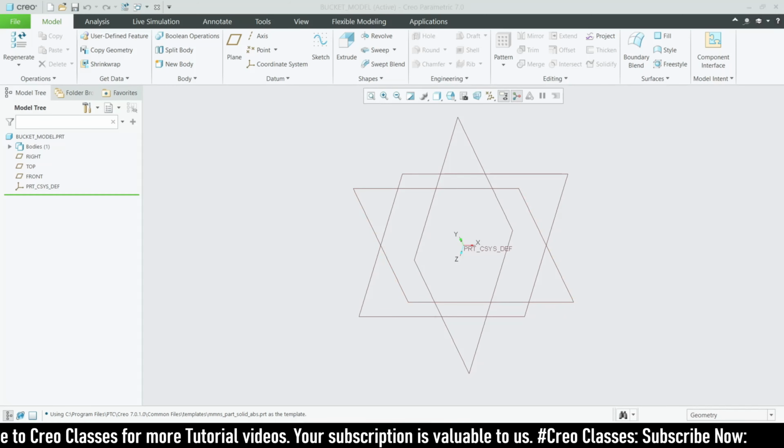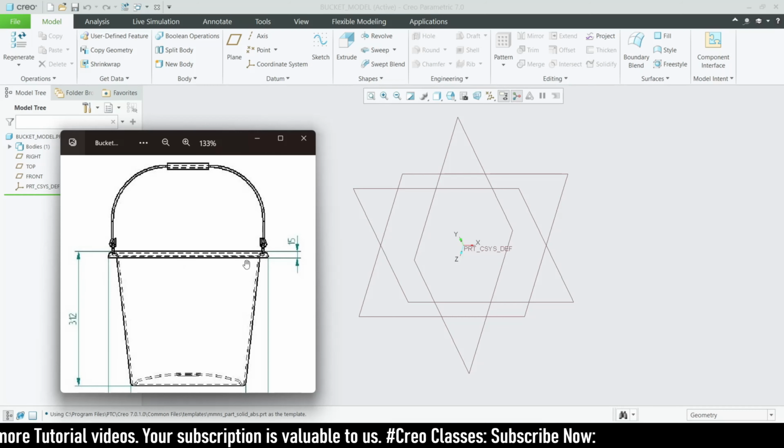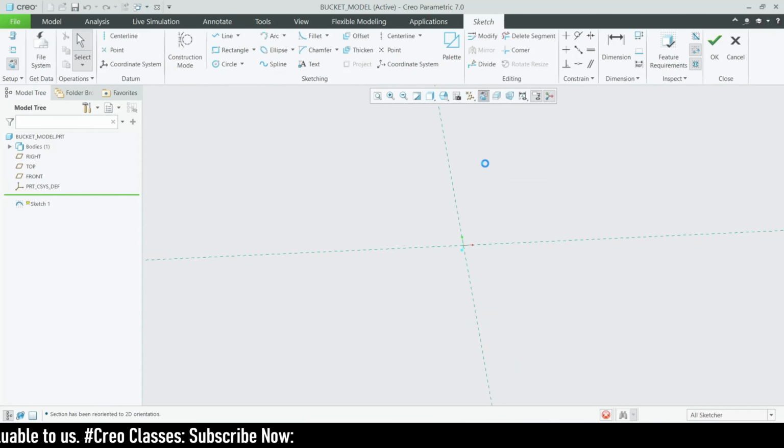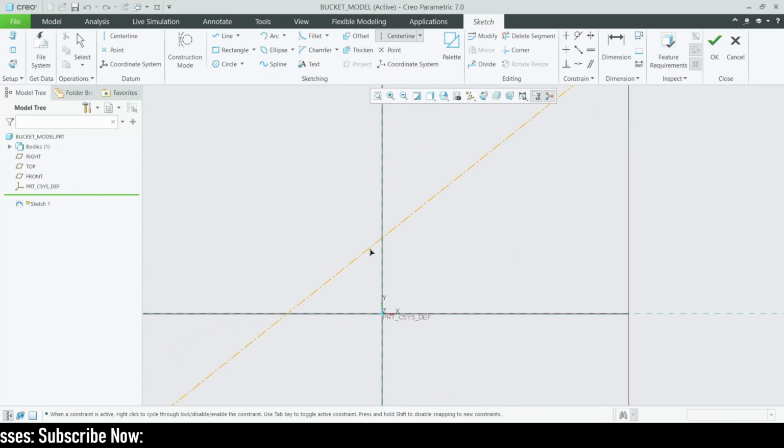So to start our sketch, I'm going to create this base part first. For that I'm going to use the revolve option here. Let's select the front plane, go for the sketch and then go for the sketch view. Here I'm going to create a center line, which is a must while using a revolve tool. Or else, if you forgot, you can directly select the axis. If you go for the revolve tool, this axis will appear there.